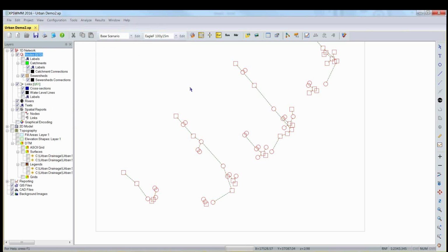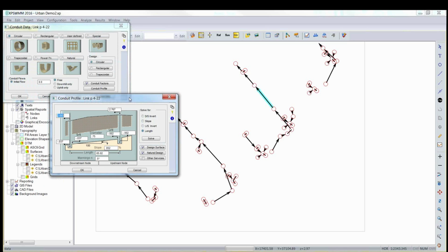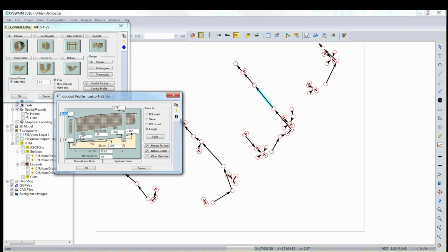So over to the hydraulics. I'm going to flick modes, and the good thing is randomly selecting this link here, 12D has been able to provide me with some information on elevations. It's a circular pipe, and we have information on the conduit profile for elevations. We're actually down near the ocean. Elevations below zero in this particular model. 750mm diameter pipe, ground elevations accordingly.